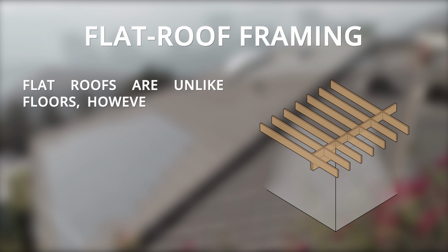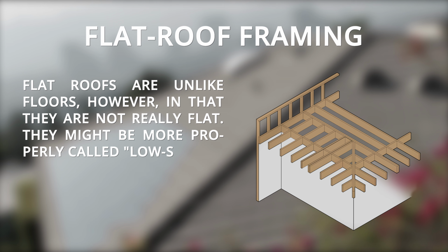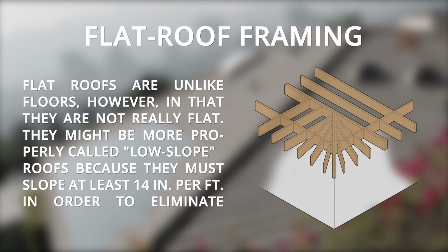Flat roof framing. Flat roofs are unlike floors, however, in that they are not really flat. They might be more properly called low-slope roofs because they must slope at least 1/4 inch per foot in order to eliminate standing water.